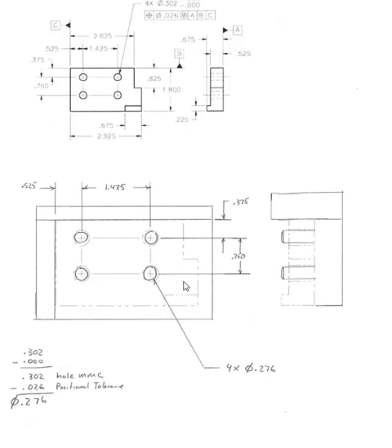That forms the gauge. And this bar here is going to pick up my datum C. Then this functional gauge is going to have 4 pins, and those 4 pins are going to check this feature control frame.